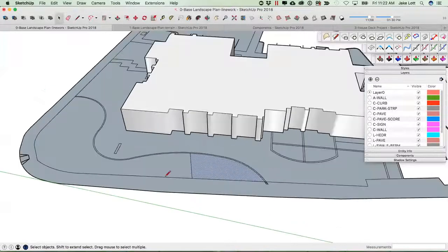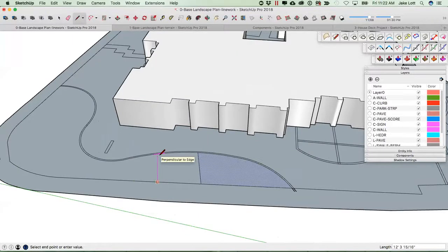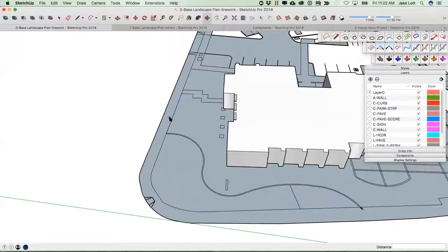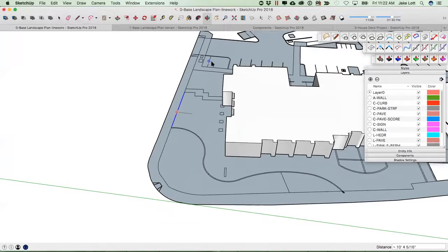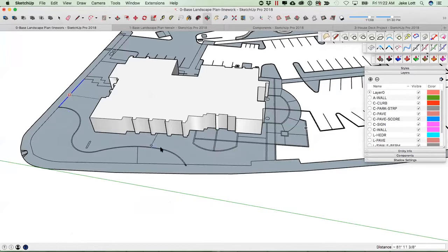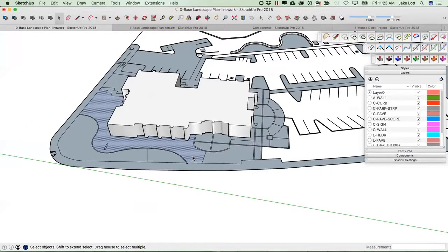without needing to use the line tool and click here and try to match it up with this line here and then click two points and potentially mess up that line. But simply using this divide face, click on this sidewalk line, it allows me to go to any one of these areas, and I know that I'm going to be parallel with that line wherever I go. So I can subdivide, and it has cut in that face. Really neat tool. I just discovered that one as I was playing around with this, so I figured I'd show that one.